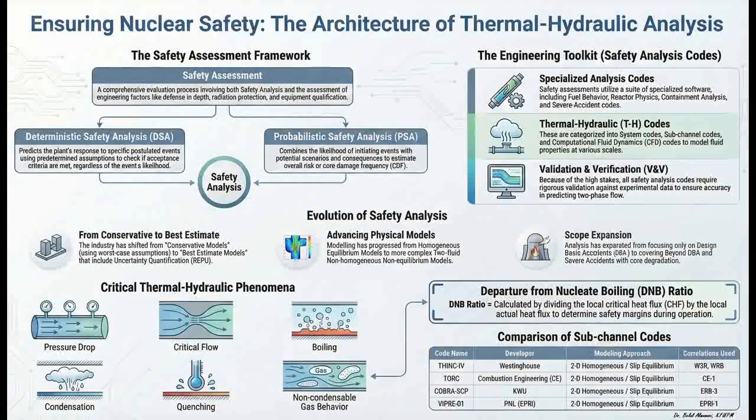So the simulation looks at the current local pressure, mass flux, and thermodynamic quality in a specific node and pulls the critical heat flux value directly from the empirical database. It provides a grounded, highly reliable trigger point for the simulation to recognize the crisis. And if the transient pushes the system past that trigger point, the code must dynamically switch its physics engine again.